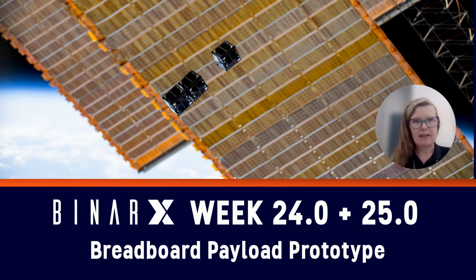And then if you can, just go through it and see how it applies to your own payloads, that would be great. You'll be using the visible light photodiode and the little op amp that were recently delivered to your schools or your teachers. And make sure you've got all the parts on your lesson plan ready to go, and you can put together that circuit, calculate the resistor you'll need, and just follow along.